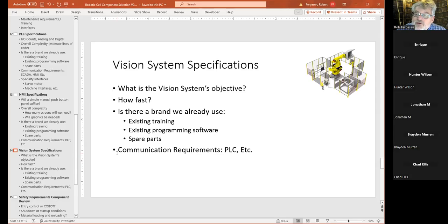The ones we have in the lab are designed primarily for quality control. They're designed to look at images and decide if the image in the snapped picture that you just took is acceptable or not acceptable. So you have an original snapped picture of the perfect product, and you compare that to the image you just took, and all right, is it the perfect product or not? If yes, I turn on an indicator to the PLC saying, yes, it's a good product. If it's a bad product, then I turn it off. And all this can be extremely fast.